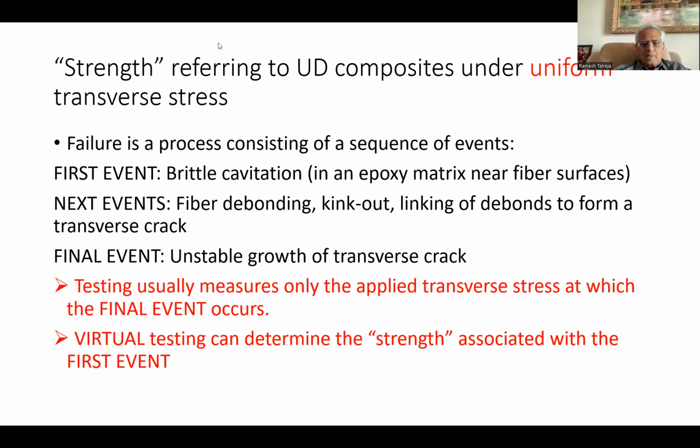Okay, so when it comes to composite materials, as I think Federico also mentioned in the introduction, it's a heterogeneous body, which means what we are applying externally on the boundary of it is not what is inside, because as the load from the boundary, or tractions, are transferred into the material, at every point in a heterogeneous body the state of stress is not uniform, and not uniaxial, it is triaxial. And because of that, the events that are going to be so-called critical, that we call failure, are going to be different.